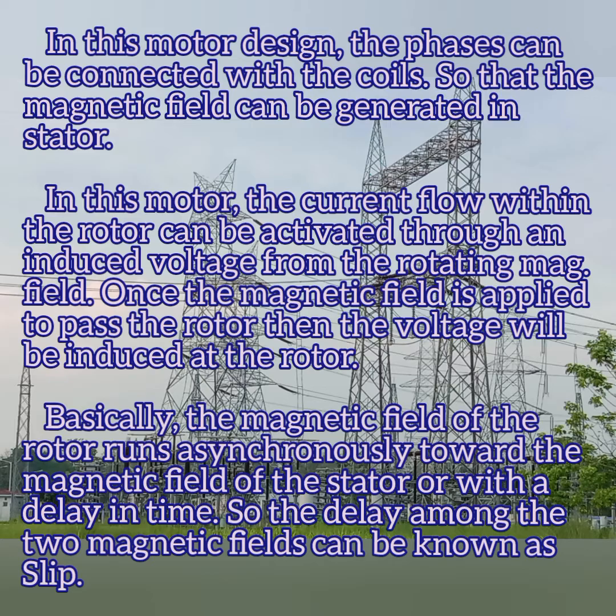Once the magnetic field passes the rotor, a voltage is induced in the rotor. So basically the magnetic field of the rotor runs asynchronously with the magnetic field of the stator, with some delay in time. The delay between the two magnetic fields is known as slip.